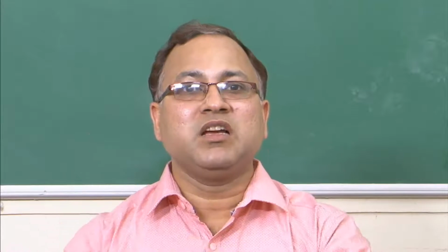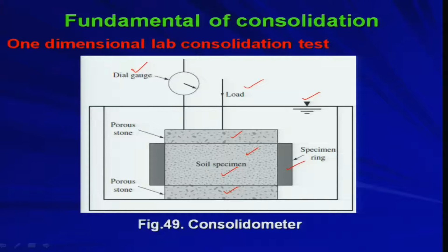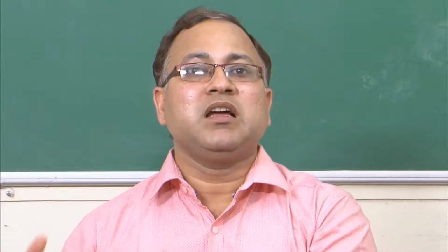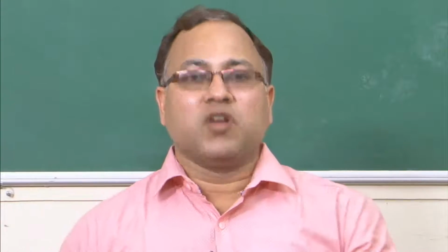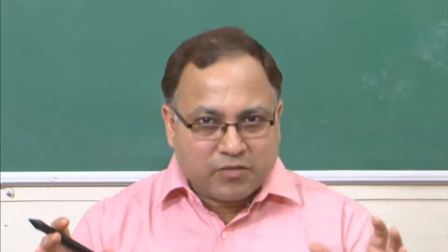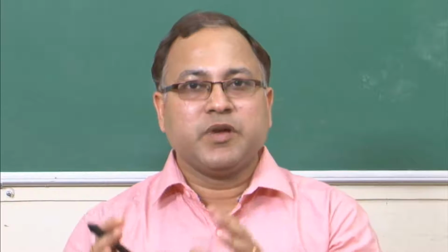Because you have the confinement in the lateral direction, the soil will be allowed to deform only in the vertical direction. So, the volume change you are considering is nothing but the change in depth of the soil specimen, because you do not have any change in the diameter. The diameter is completely confined, and the soil specimen will deform only in the vertically downward direction. So, whatever volume change you observe in the soil is equal to the change in height of the soil specimen, am I right? I hope that you have understood the laboratory experiment concept.